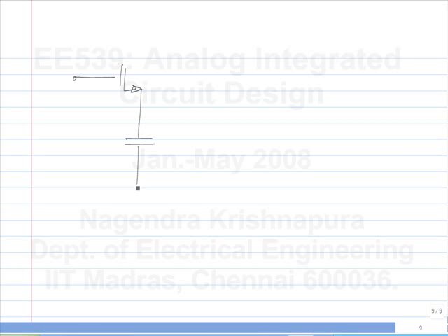A common drain amplifier could be loaded by a capacitor. After all, it is used as a voltage buffer. And you will have a capacitance, it is the transistor's own CGS plus any other parasitic capacitance. So what does it mean? If you make a common drain amplifier and load it with a capacitance, the input impedance will have a negative real part.